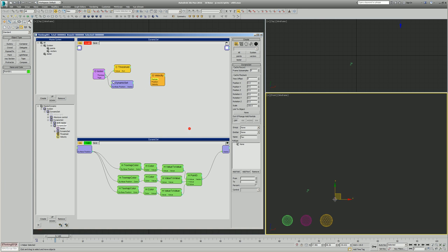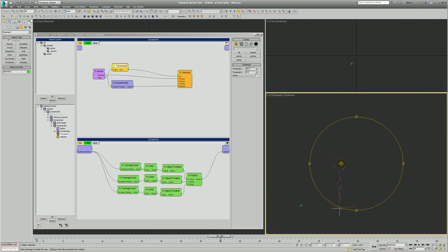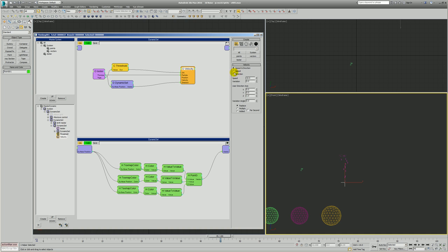Now, I know what's going to happen as soon as we do this. We're going to expose our direction here from the noise field. It's going to be too strong, most likely. And so our particles, yeah, you can see right now they basically get slammed like that. Let's have this just control direction as well. Boom, boom, boom. So, there we get some noise field. It's a pretty good size.